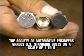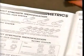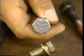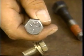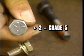The Society of Automotive Engineers grades U.S. standard bolts on a scale of 1 to 8, grade 1 being the weakest and grade 8 being the strongest. To identify the grade of a bolt, count the number of lines or marks on the bolt head and add 2. The bolt shown has 3 lines stamped in the head, indicating it is a grade 5 bolt.